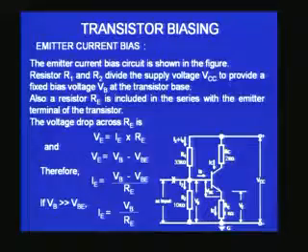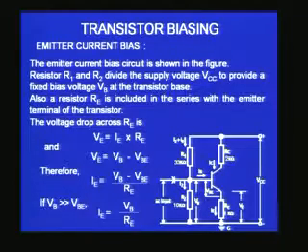But you have another problem in this. Any amplifier, and this becomes an amplifier later on, the input impedance or the input resistance, that is the resistance as I look from the input side into the amplifier, should be very large. Why, etc. we will discuss at a later stage, but in principle now let us assume the input resistance in general to a good voltage amplifier should be very high, and that will be ensured only if I choose my R1 R2 values very large.